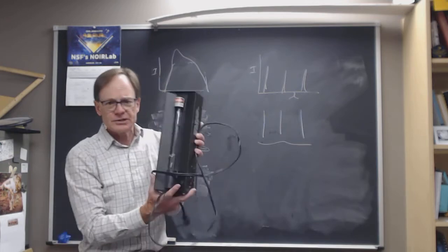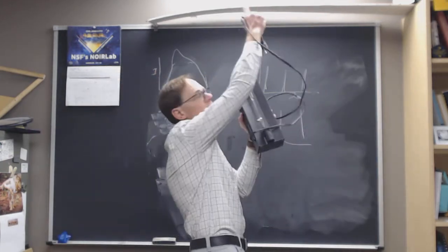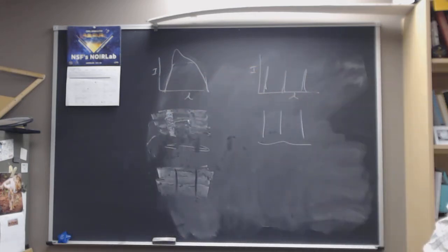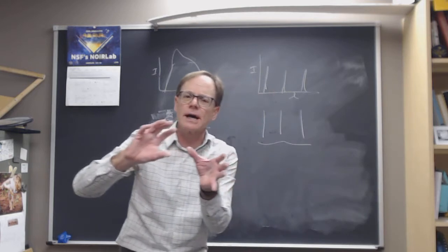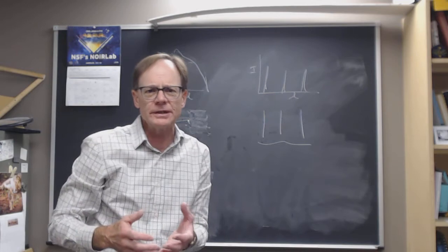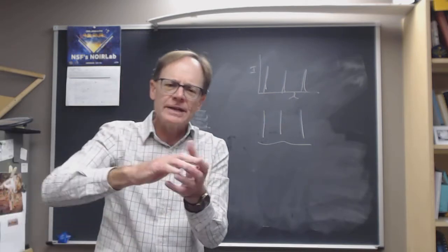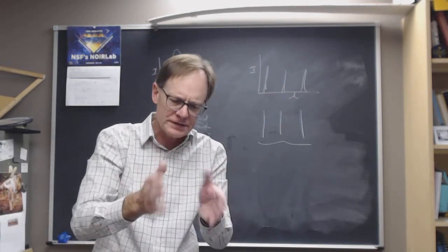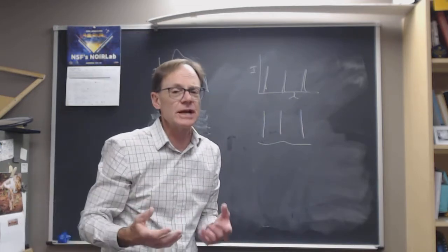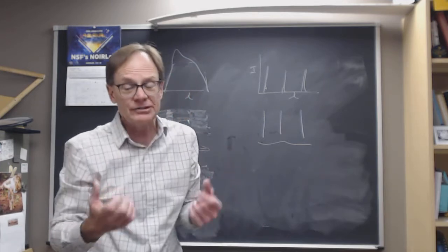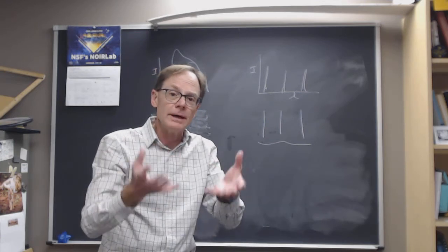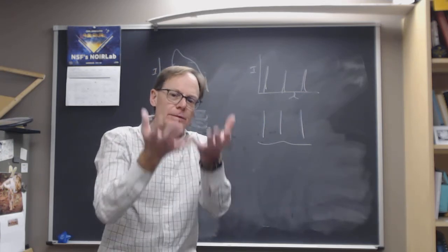So what you do is you have a lot of sources like this, or the sun, or the fluorescent light overhead. An incandescent bulb is a great light source. If you have an incandescent bulb, you can put it on a variac, and change the voltage. A variac's a variable power supply, and if you change the voltage across the filament, that's changing the current through the filament. It's changing the temperature of the filament. And as you change the temperature of the filament, the intensity of the light bulb changes, but also the color of the light bulb.